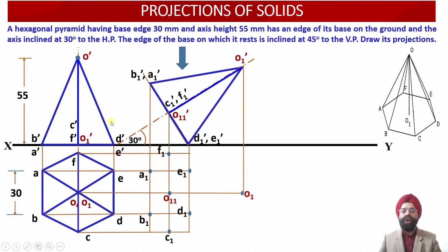Let us look at the solid from the top. As the observer is going to look at the solid from the top, the points which are farthest away from the observer are D1 dash and E1 dash. It means that these 2 points are not visible to the observer. So in the top view, anything joining D1 and E1 should be drawn using a dotted line, unless those edges fall into the boundary of the object.